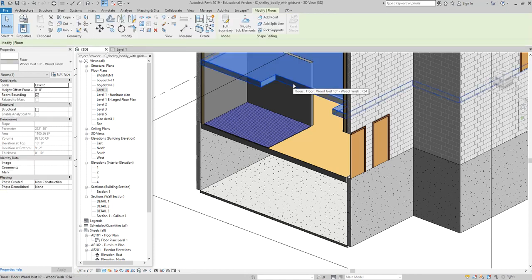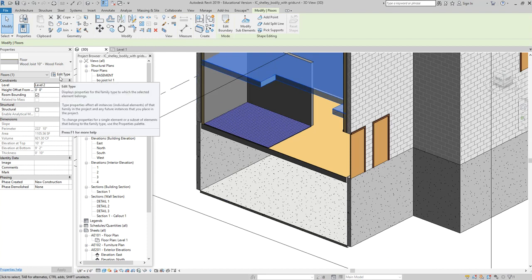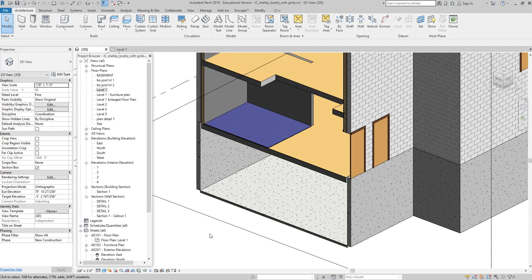So when I want to create a brand new type, I'm going to select the ceiling closest to the new type I want to generate, hit Edit Type, duplicate, rename, redefine, and use in your project, okay? So that is sort of the definition of a ceiling. They're elements that will host other items like lights, as we've been talking about.